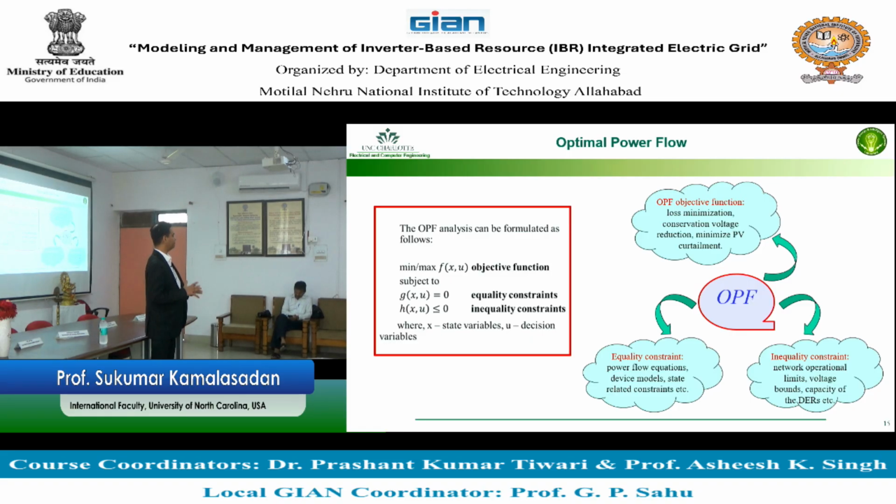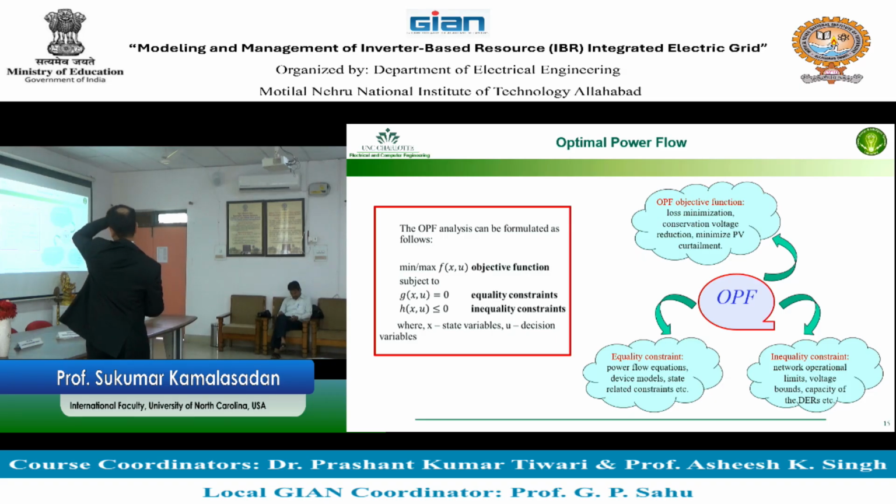Optimization feasibility is whether mathematically you can solve the problem or cast the problem in the form. Power flow feasibility means, I cast the problem, I solve it. Is that really good? It's all solved, but the voltage is 0.45. And so it is not feasible. You did solve it, the method is there, nothing is breaking, and the software is working, but it's not feasible to implement. So feasibility of a problem has two different aspects: mathematical feasibility as well as implementation, whether it's feasible or not.